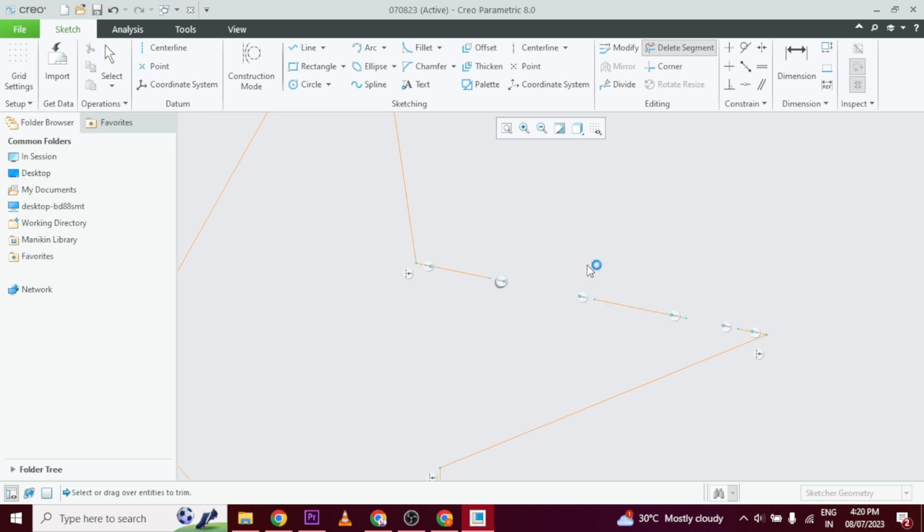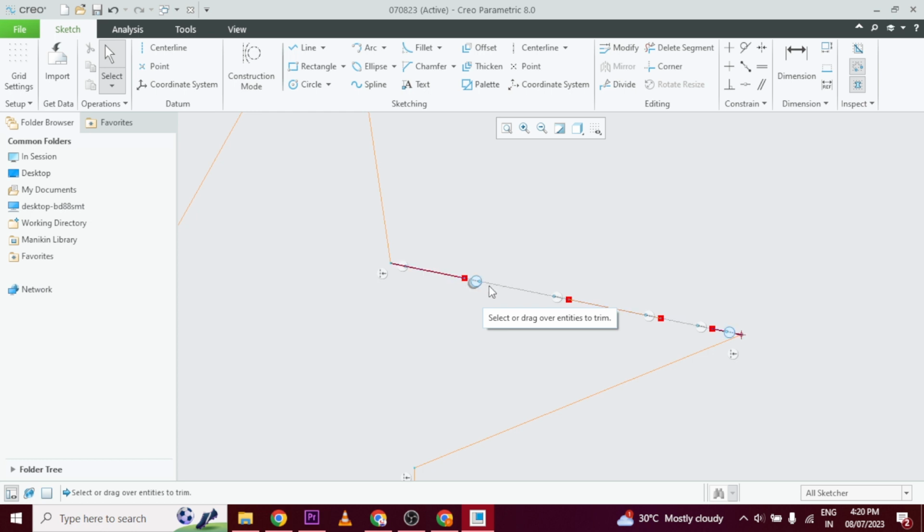Now if you drag it, just simply Control Z. If you drag this line, the whole structure is getting displaced, because some relations have been created here, that is, a point on extension line, that is this one. Now if you remove that constraint, simply click it and delete it, likewise here click it and delete it, then the line is free, I think.